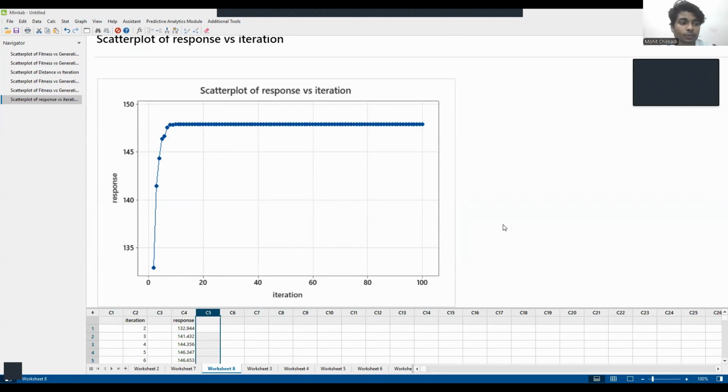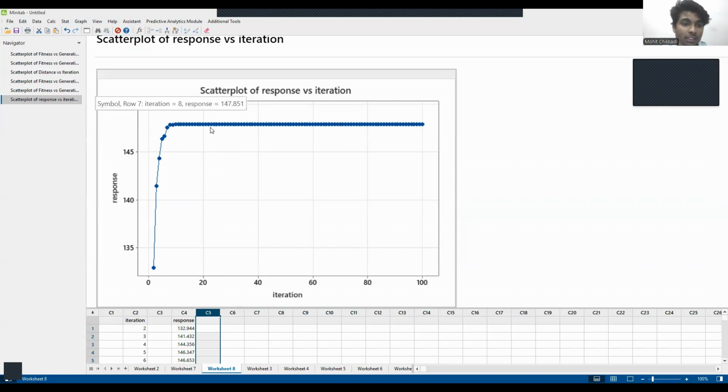Now we can see that the DTBO rapidly converges to a highly optimized solution, reaching its best fitness at the 30th generation itself. And this method effectively balances the robot's speed with tilt control, ensuring smooth and efficient movement. The DTBO optimized parameters showed significant improvement in reducing the tilt angle and deviation. This means better handling under various load conditions, which is crucial for a cafeteria environment.